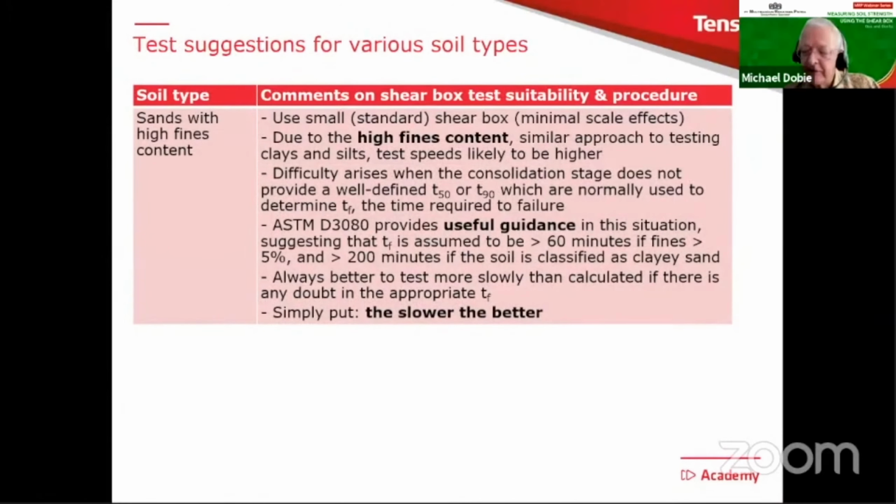Let's move on now to the next type of soil, sands with high fines content. Now we can use the standard or small shear box. That's okay, because we're not going beyond the sand size. But the problem is that with a high fines content, you may run into similar problems as we see with the clays and silts when it comes to the issue of pore pressure. Therefore, we also need to be careful about the rate of shearing, but unfortunately in these sorts of soils, sometimes it's difficult to measure T50 or T90.